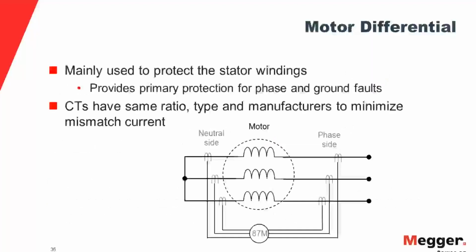The voltage and current measurements at the local end are also sent to the remote end through the pilot wires, and the current comparison happens at the remote end as well. If there is a difference of current between these two ends, then the relay will operate immediately. Typically, the percentage differential is implemented to compare the currents from either end of the transmission line.